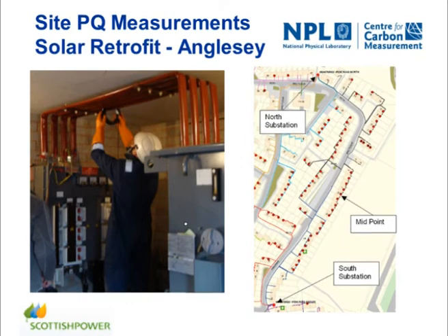There was some monitoring done at various points by Scottish Power and also by us in the North substation there. And you can see one of the Scottish Power engineers, Ken Lennon, there with his very special rubber gloves on, fitting one of our transducers to the bus bars in this substation. This is something called a Rogowski coil. It's a split device which is effectively held together with Velcro, and Ken is wrapping it around the bus bar there so that we can measure the current flowing through those bus bars in the substation.